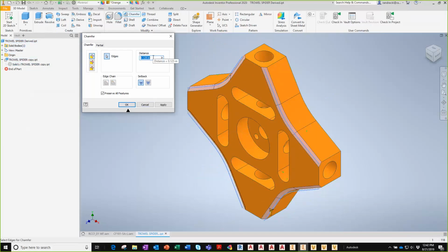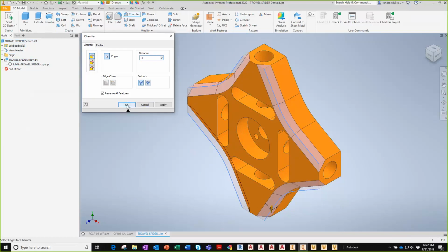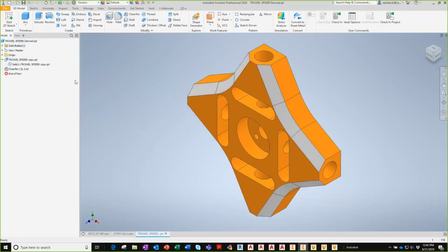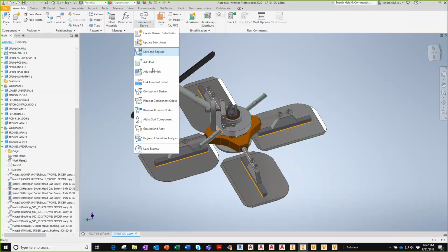And we'll bump them up to, turn my numlock on, 0.4. There we go. And we'll reduce it a little bit. There we go. So we've made a simple change to the Derive part. Save it. So quick Derive part. Takes us into the next command, which is